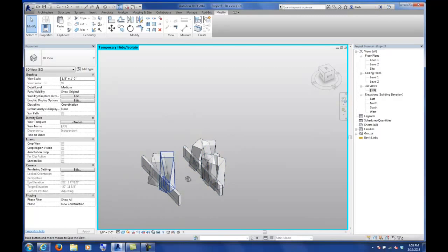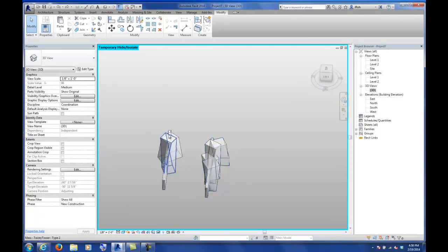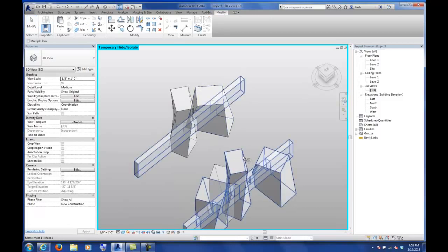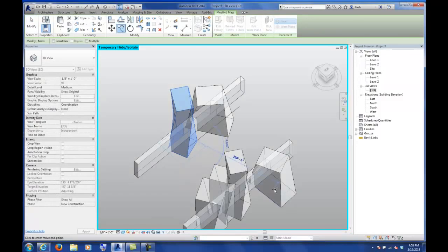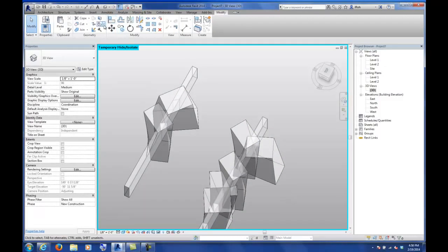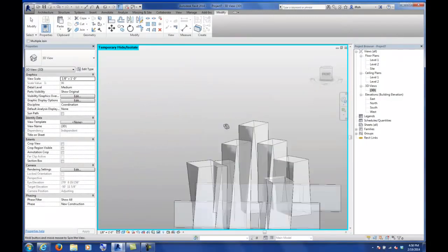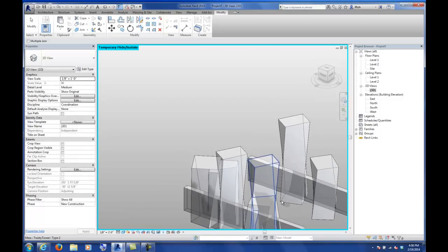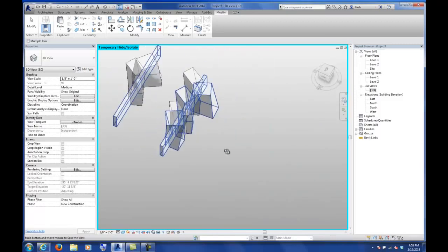So the other part about this is that once you've done all of your different cutting, you can also join these components together. Instead of cutting, I could just click on join, and let me make another tower over here. If I click these two together or make them overlap, instead of cutting, I could also join solid geometry. Whichever one you selected first has priority, but it becomes one component that's joined together. Kind of looks the same, actually.